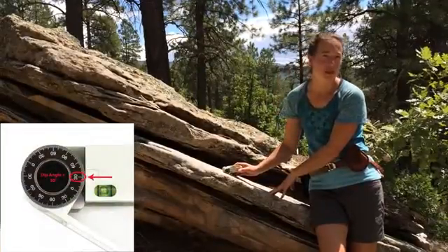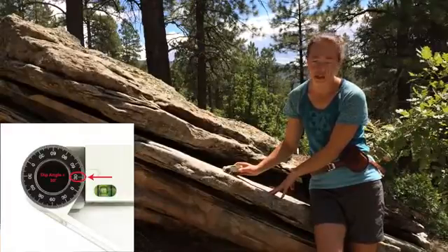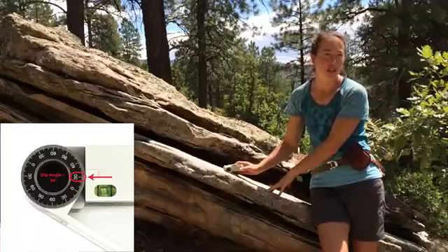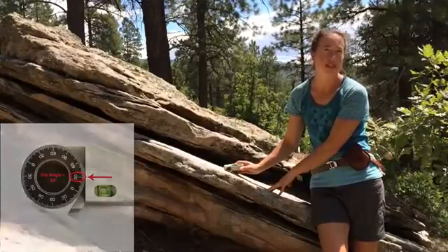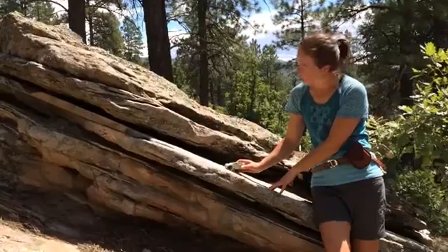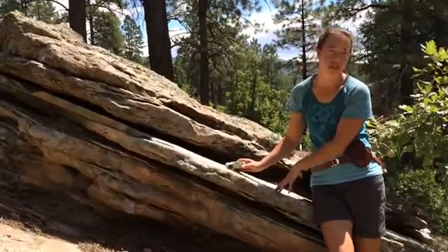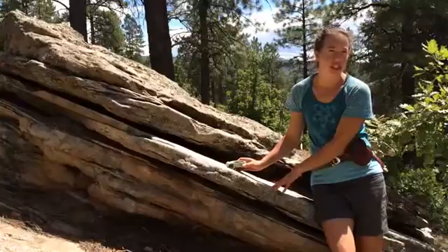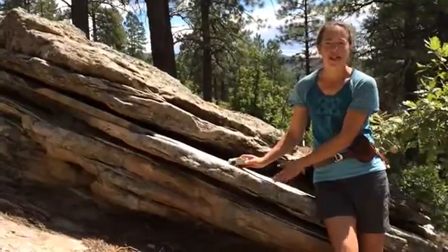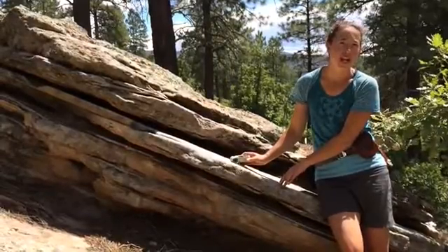If this is hard to remember, just look closely at the hinge dial marks. Only read them where the hinge dial is perfectly aligned with the dip indicator on the compass in order to avoid errors and confusion. Most planes can be measured with either lid configuration. You'll get used to which is easier and which you prefer for particular situations. So now let's take some strike and dip measurements of a variety of different planes.